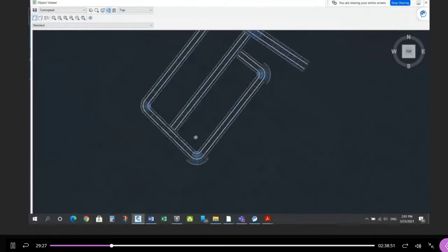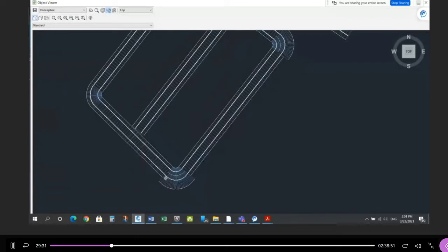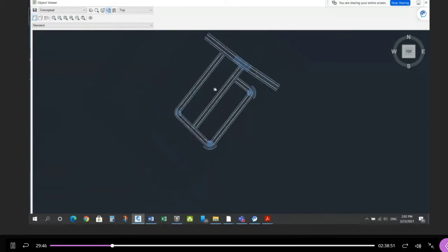And the other thing I look for, like I said, sometimes you see a spike at the beginning or at the end of the corridor model. Because remember, the horizontal range is greater than the profile range. So you get 0 spikes at the beginning, at the end of every alignment, including the gutter alignments.